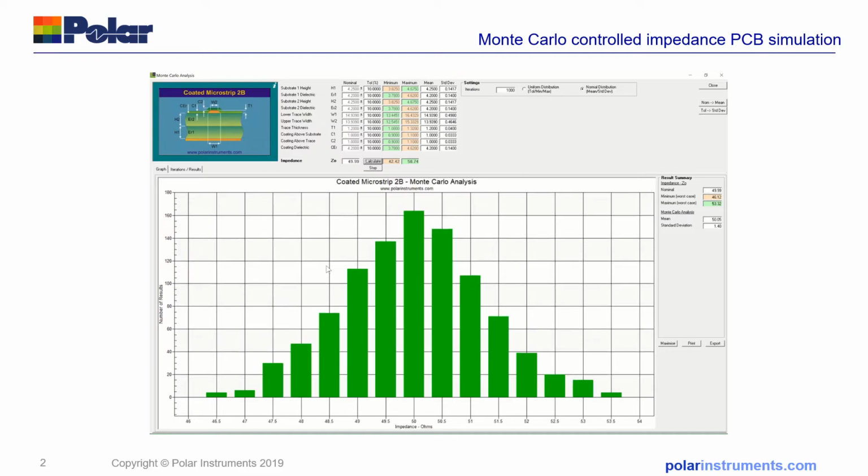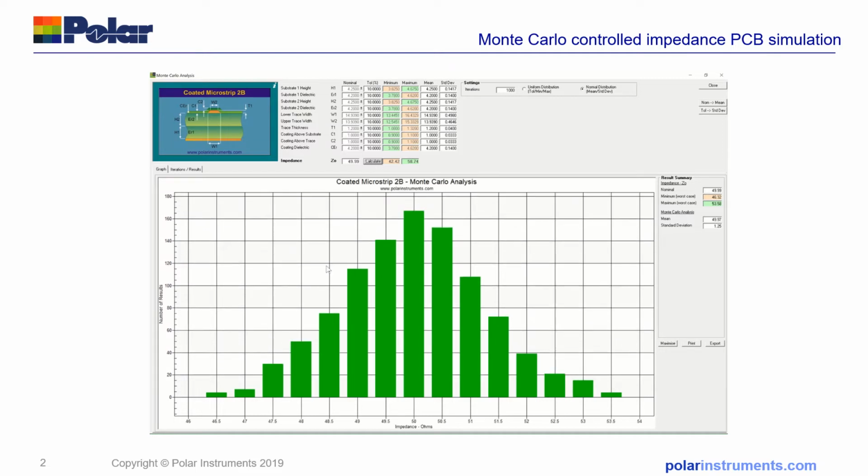You can adjust the tolerance to reflect real life. For example, often the coppers are made to be close to their nominal minimum thickness, and so you can set the copper to be its expected deviation. Or if you know more about each material than the datasheet predicts, you can modify the inputs to the Monte Carlo analysis to get yourself a realistic picture.